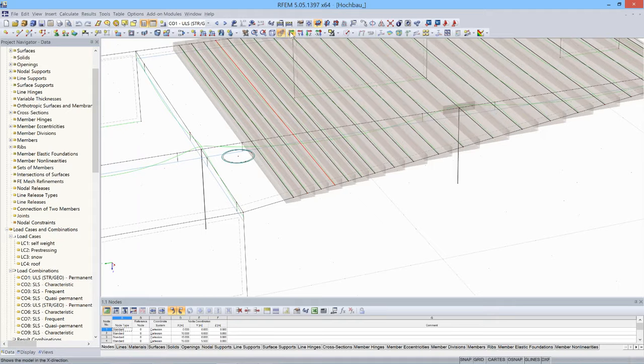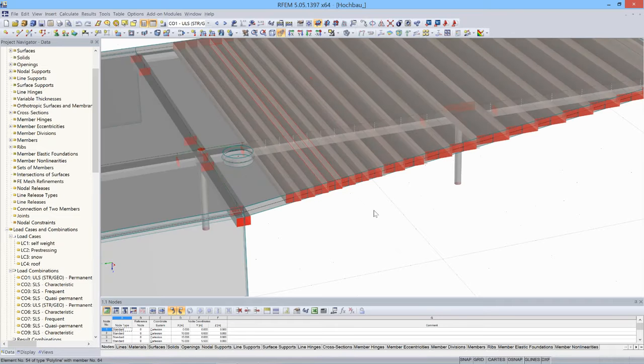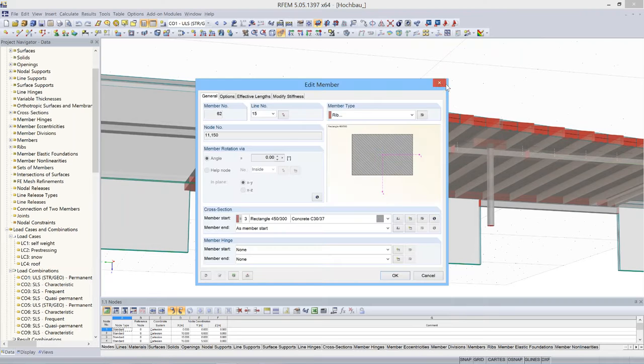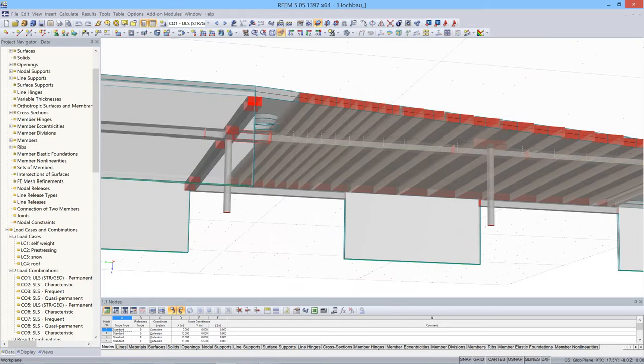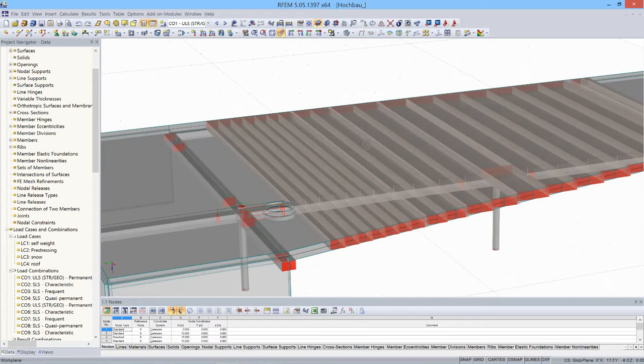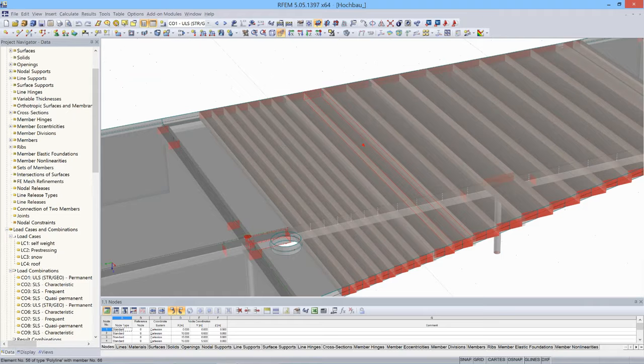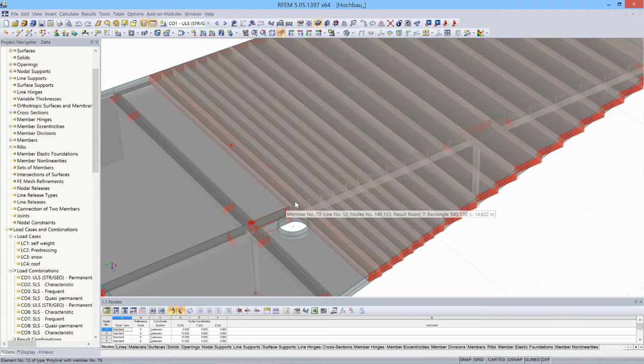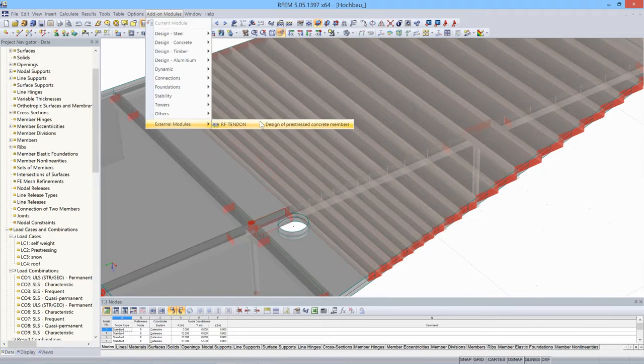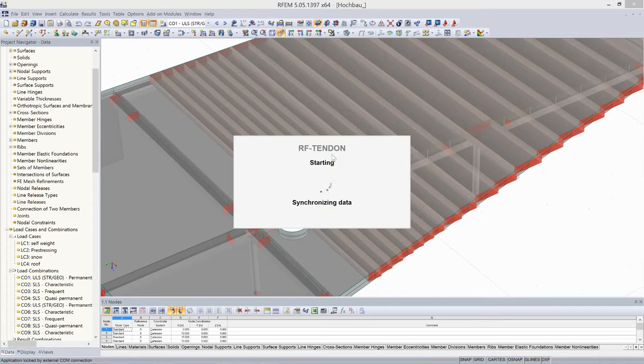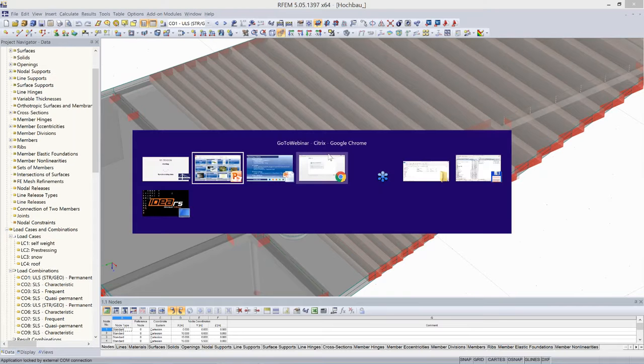Last one which I want to show is this beam and slab system. You can see here that I have a rib which is linked to the slab, and RFEM can integrate internal forces from a defined width of the slab together with the rib, and we can get a T-section, which I will show, which then is used in the analysis and in the design.